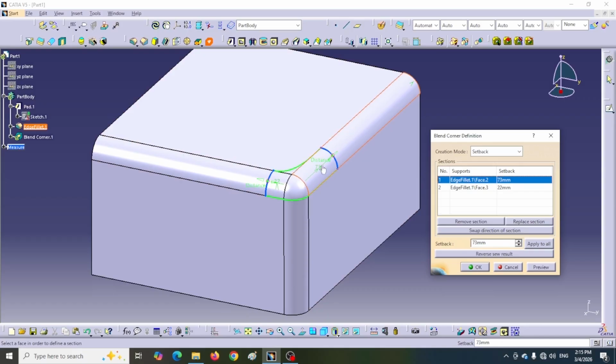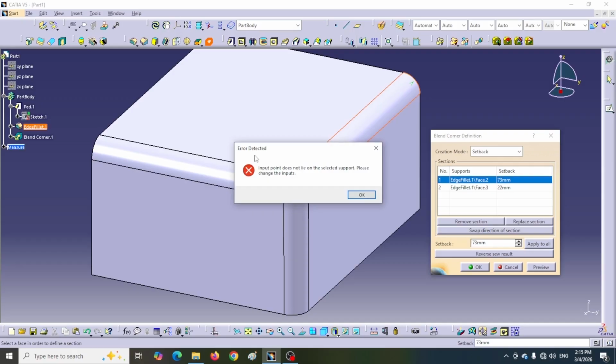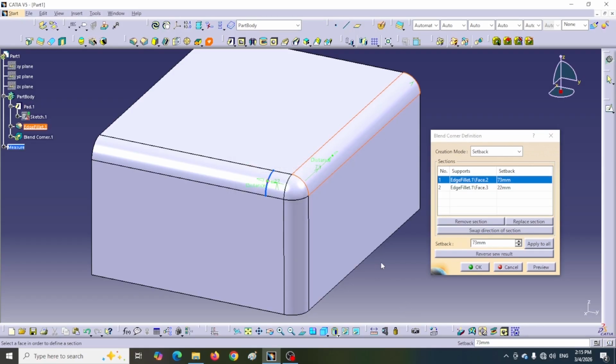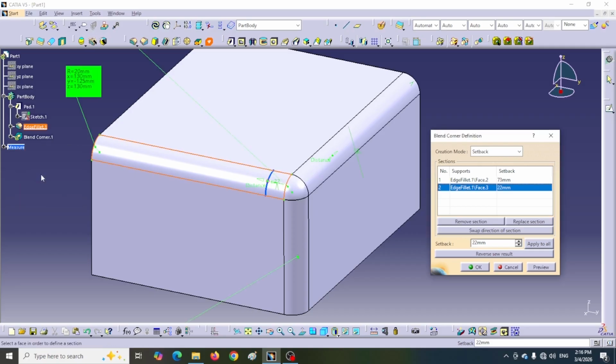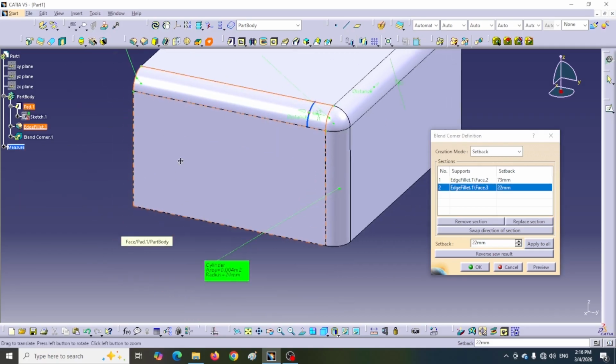The size of the fillet's radii and the amount of setback on them affect the possibility of the swap operation. For the swap operation to be possible for any fillet radius, only a certain amount of setback can be increased. Currently, the fillet radius is 20.